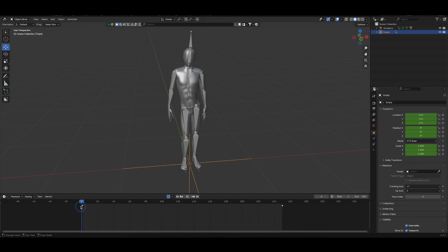But the one thing I don't like about that, maybe sometimes it's quite convenient, but what we actually don't need, is that Blender automatically creates ease in and out animation for any keyframes. You see that it's going a little bit faster, accelerating, and then it slows down. We don't need that, we want to get linear animation of the rotation.